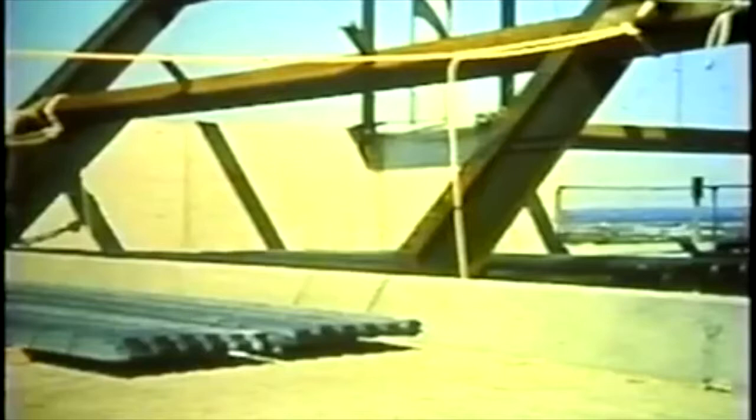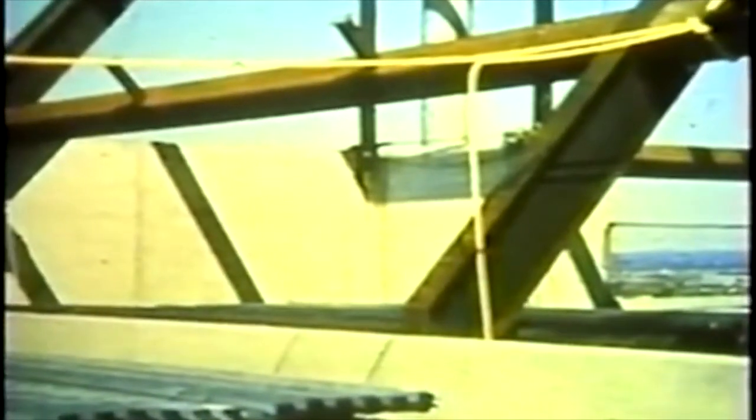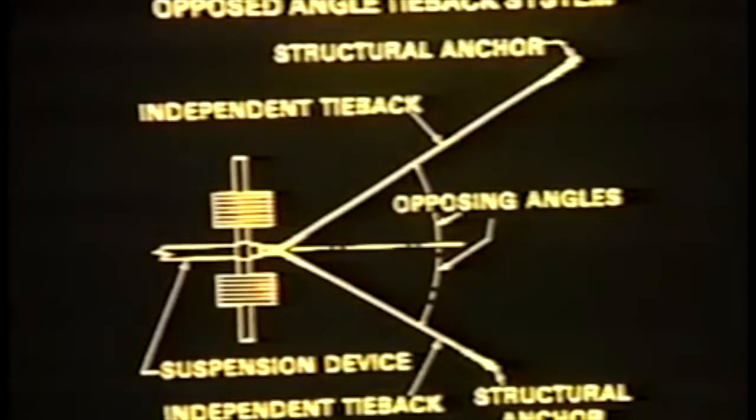Tiebacks of 3/4 inch manila rope or equivalent shall serve as a secondary means of anchorage and should be installed whenever possible at right angles to the face of the building and secured to a structurally sound portion of the building. The sheaves of all blocks and the hoisting mechanism must fit the size of rope used.